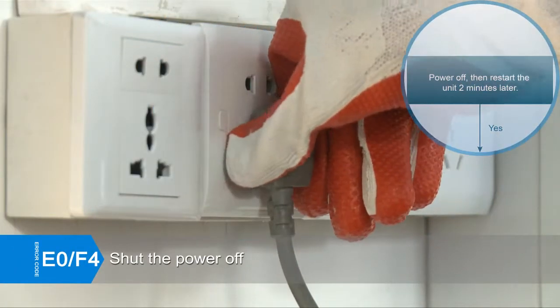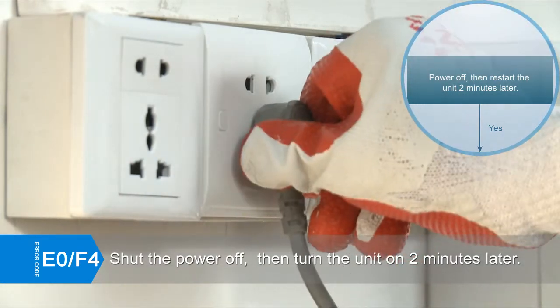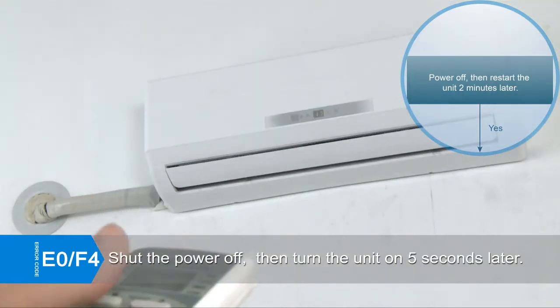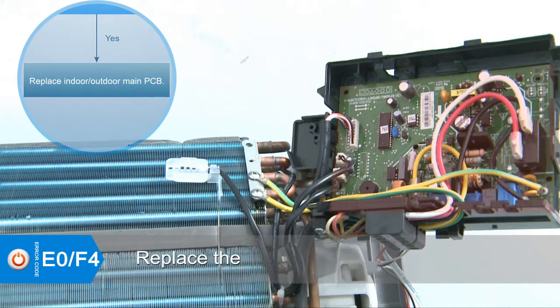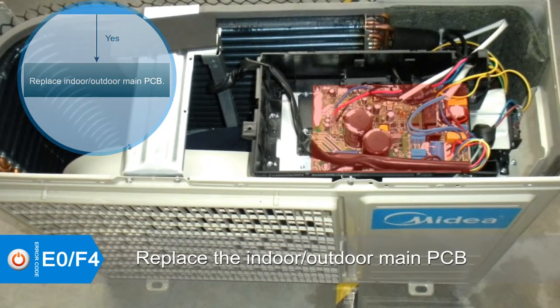Shut the power off, then turn it on 2 minutes later. If it is still displaying the E0 error code, then replace the indoor main PCB. If it is still displaying the F4 error code, replace the outdoor main PCB.